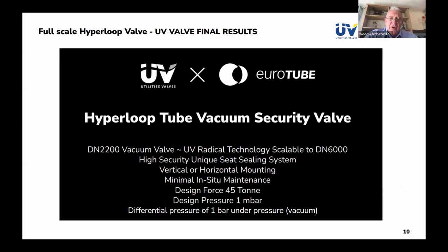But we will also look at any inline maintenance that may be required as part of the study going forwards. Design force we've mentioned earlier. Here we've got 45 tons acting on the door with a design pressure of 1 millibar and a differential pressure of 1 bar under pressure vacuum.